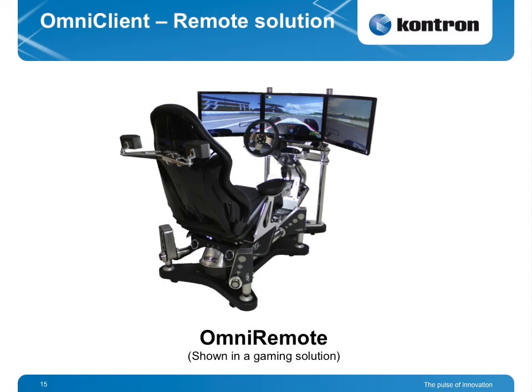The true representation of what the Omni Remote would be used for would be where the display can be next to the machine, but the processor is protected away, maybe underneath the machine, under an access panel. So it's not in the extreme environment that the display would be in. Because the rear section is only an IP20, which is ingress protection, there may be high humidity, high smoke, dust, so you want to protect that one. But the front panel is actually an IP65, which means you can spray it with water, etc. And this is a lot more fun than putting it on a machine.